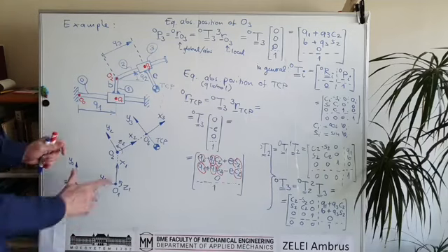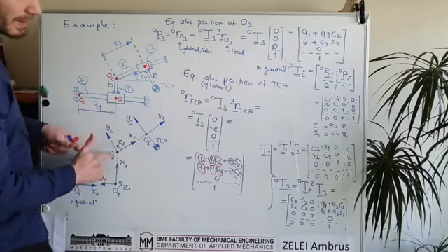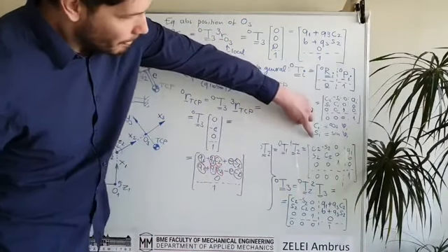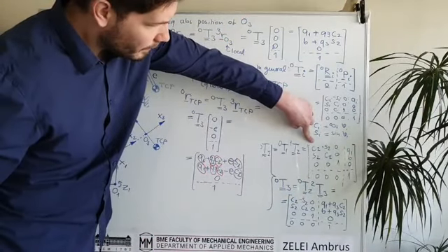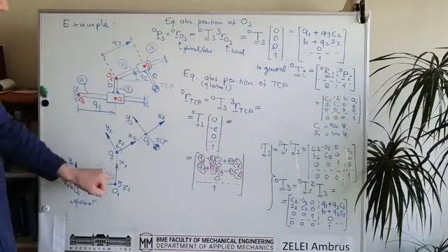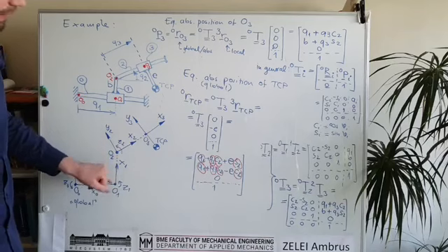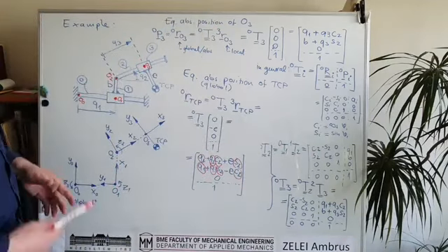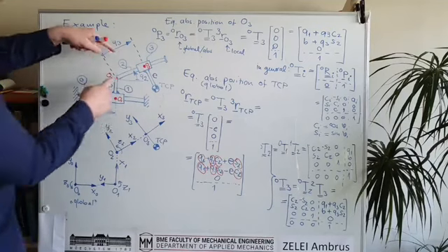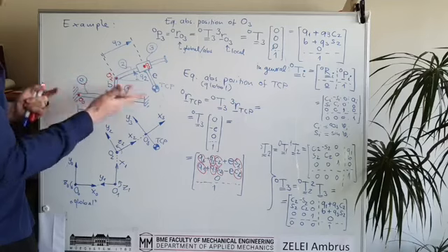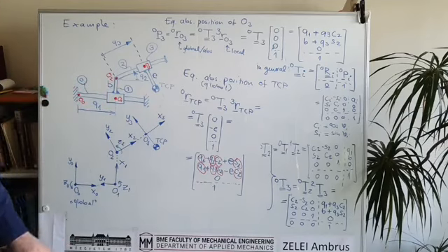But for example, if I just take the second coordinate system, its orientation and position is just affected by Q1 and Q2, so up to the second joint parameters, and of course it does not depend on the third joint parameter. So the position and orientation of the second link just depend on Q1 and Q2. This is always true for serial robots.